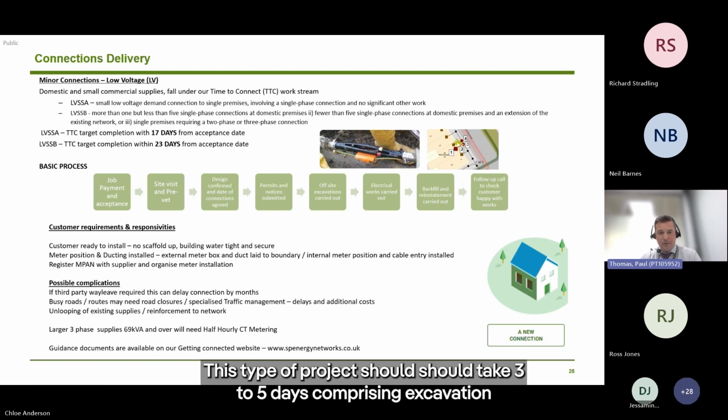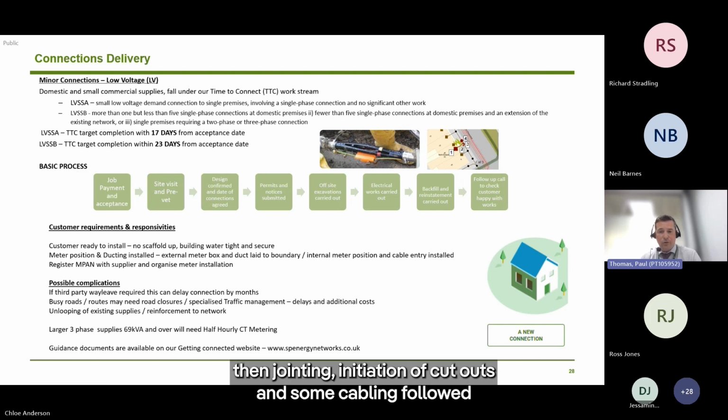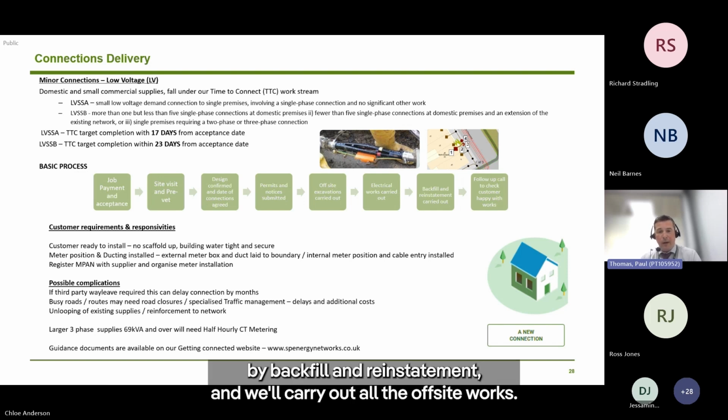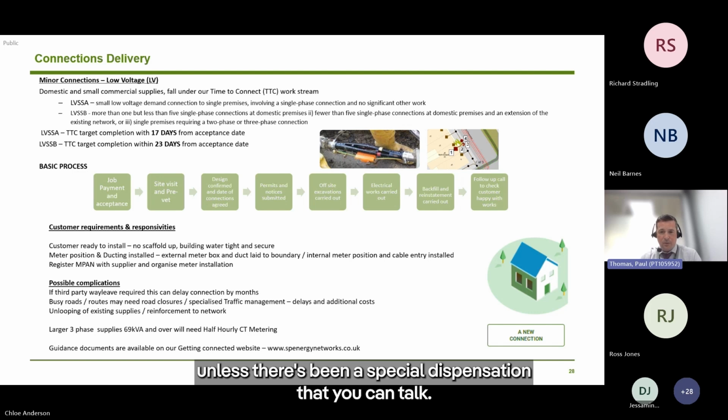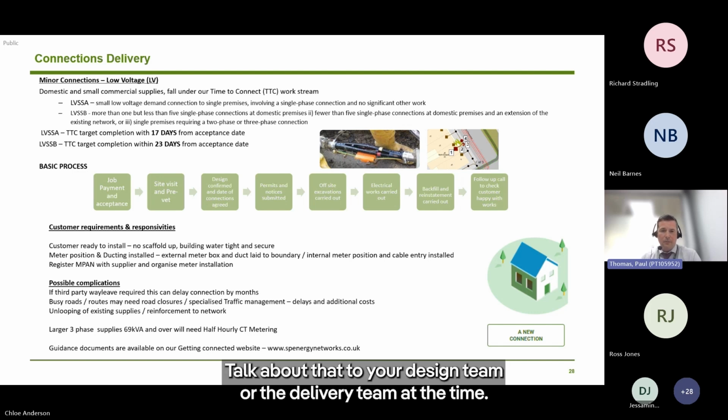On site for this type of project should take 3 to 5 days, comprising excavation, then jointing and installation of cutouts and some cabling, followed by backfill and reinstatement. We'll carry out all the off-site works, but anything on site we'd expect you guys to do, unless there's been a special dispensation on that. But you can talk about that to your design team or the delivery team at the time.